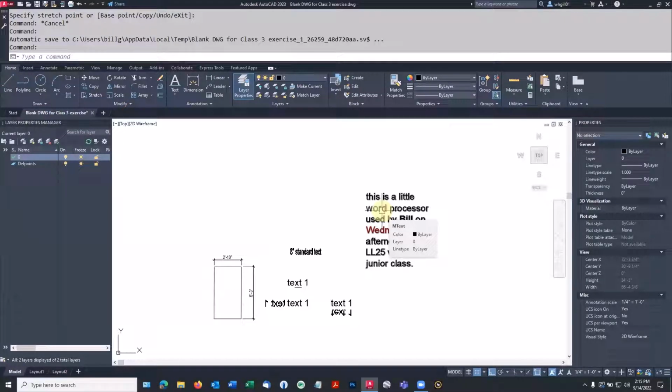So now we have to think, if I want it to plot at 1/8 of an inch, how big does it have to be actually in my drawing to come out that way? I'm going to do it graphically, okay? I won't tell you how often I've done this. So the question is, how tall is that in this drawing? Well, it's 1/8 of an inch right here, but we have to give it its scale in terms of drawing units.